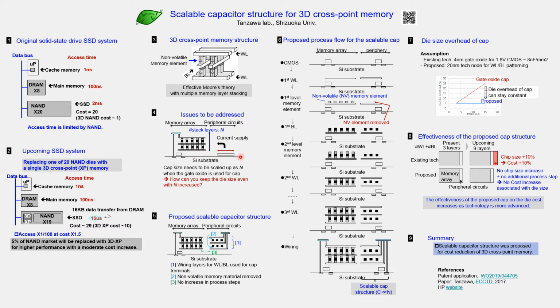And on-chip boost converter has relied on on-chip capacitors whose capacitor density is given by the gate oxide of transistors. As long as your supply voltage remains the same, such as 1.8 volts, then your gate oxide thickness is also constant.